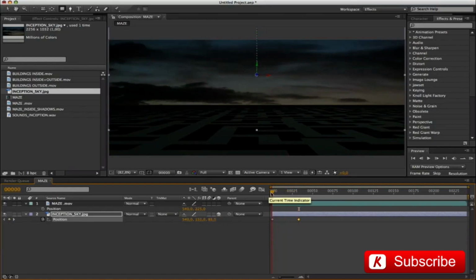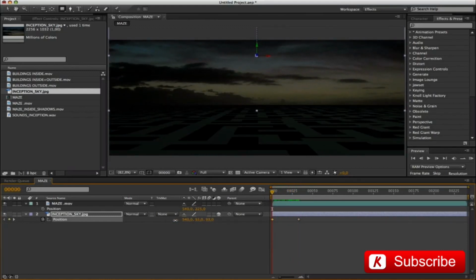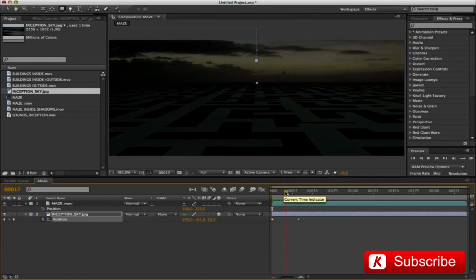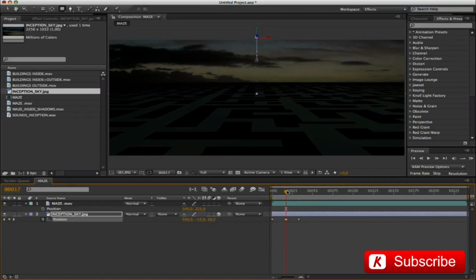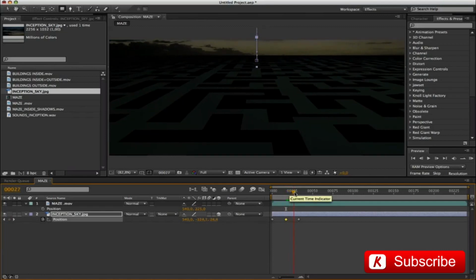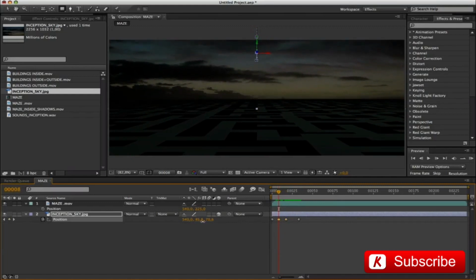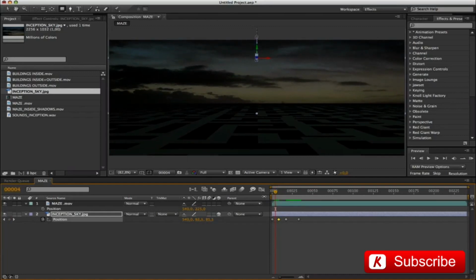As we can see, the sky animation doesn't follow the linear movement of the maze. Lower the value from 131 to 72, so as to bring the same cloud in the horizon. Insert other intermediate frames in the first part of the animation, in order to make it more accurate throughout the movement.